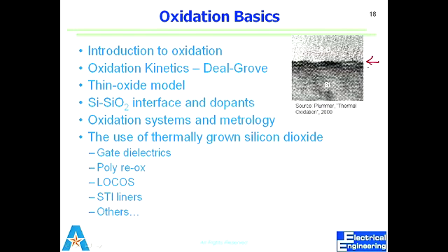As a very simple discrimination of whether we use wet oxide or dry oxide, just remember that dry oxide is slower to grow. It is very fine in quality. It grows slow, so throughput is less, but we use it only for gate oxide, because at the gate we need fine quality oxide.